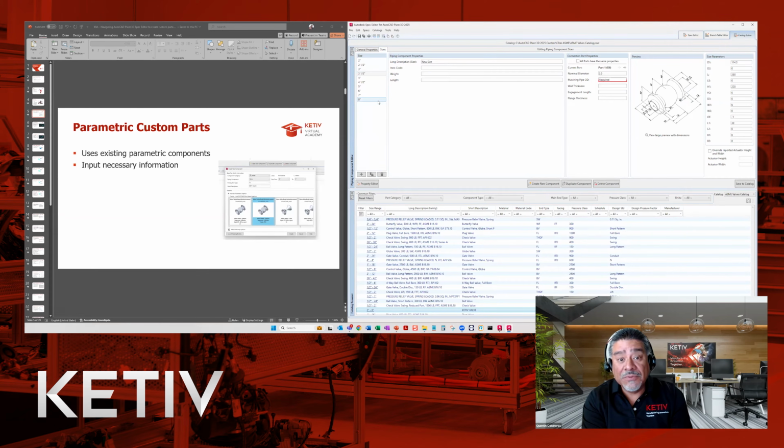Also, when I put in my size range, it gave me all the sizes between 2 and 8. If I didn't want one of these sizes, I can select these, and then I can remove them from the list here. So if I didn't need these 1/2" ones, I could take out these, and so forth. So there were sizes in here that didn't really pertain to this component. Then I can remove those and just leave the ones that I need to update with the information.